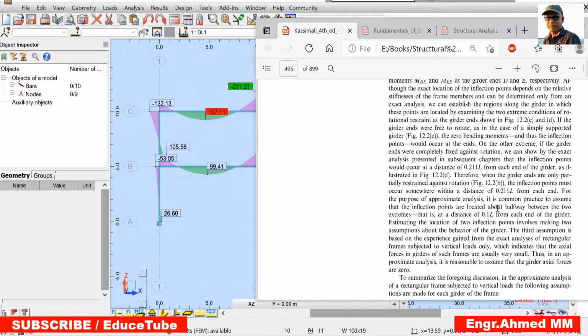But in our case, we are taking 0.1 L from each end of the girder. So I'll show you how to take those points. Once we put that, then we'll check our moment diagram again, whether it is coming very close to that value or not.